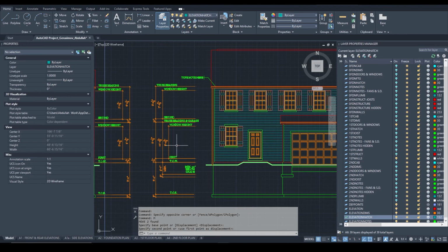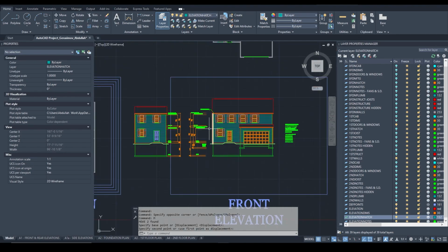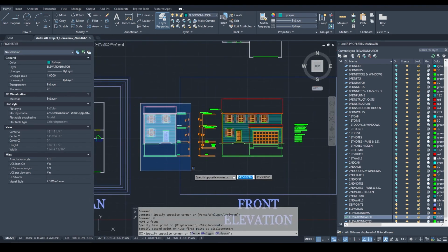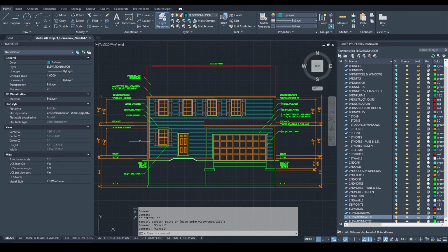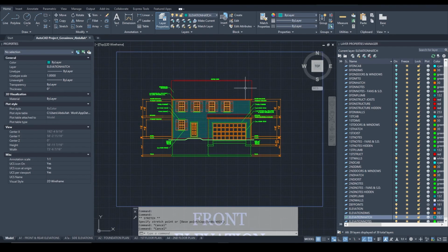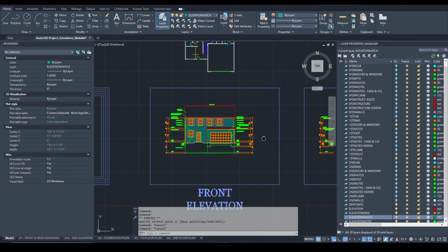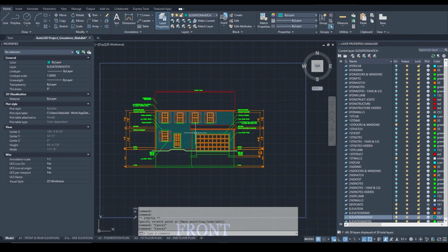Make sure as well that you're going to align the section of dimensions on the left side to the building. Remove the reference since we're not going to need it. And this is going to be the final look of your front elevation. It doesn't show exactly every single thing that needs to be on the construction documents, but it shows about 85 to 90% of everything you need to do. Again, we're not going to worry about the rest of the elevations in this class, but the concept is very clear. This is what it's supposed to look like.